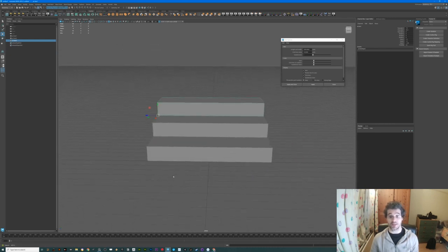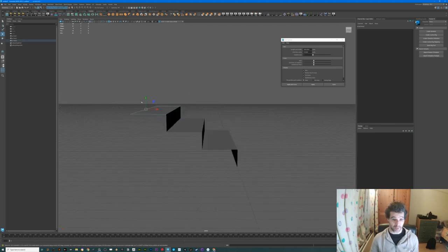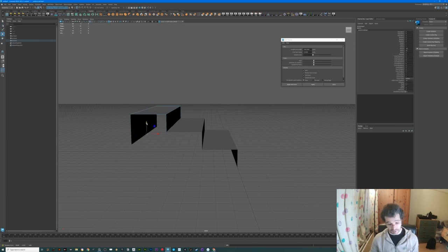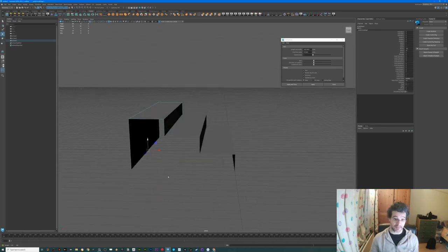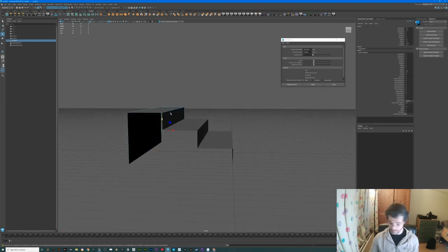ones. Right now, I'm going to come to this one, select the edge mode, and once the locator comes up, I'm going to hold the shift key until we get the extrude name on our locator and press it down. Now I'm going to hold the X key and take it all the way down until it hits the grid again. Then I'm just going to come back to object mode by right mouse click. So right mouse click, object mode.